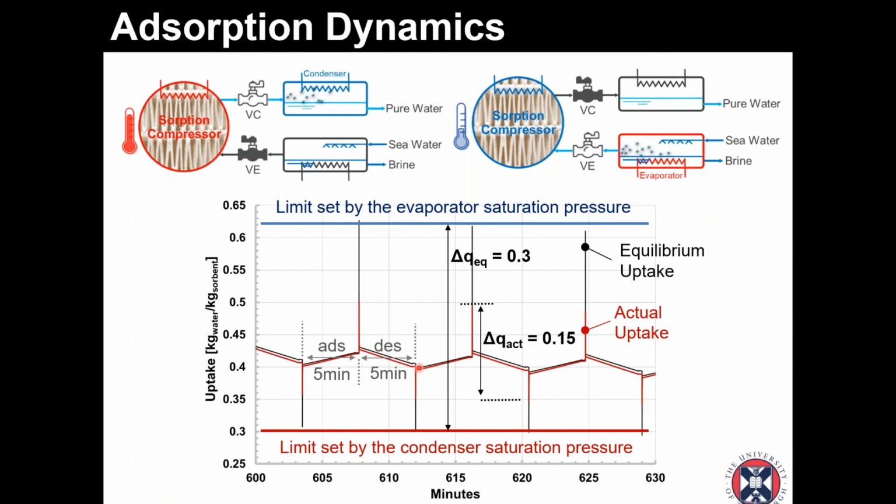So the message here is that the change, which happens mostly here, so the curve is going down and then down, so this step is the majority of the working capacity, and this step here as well happens every time we have a change of relative humidity. So it's the change of relative humidity that makes really the difference, rather than the heating and cooling of the bed.